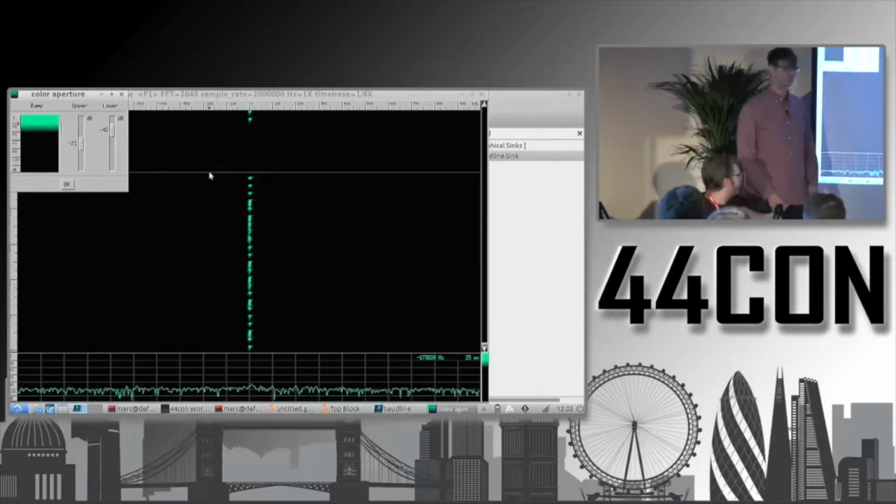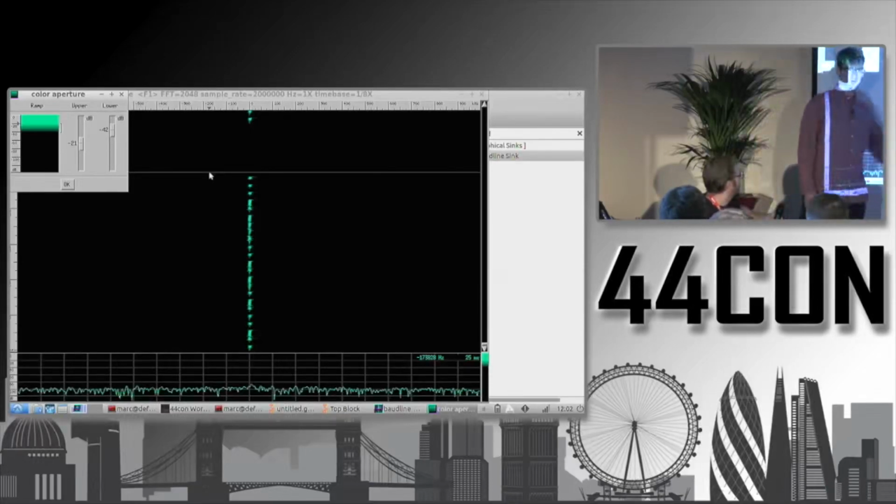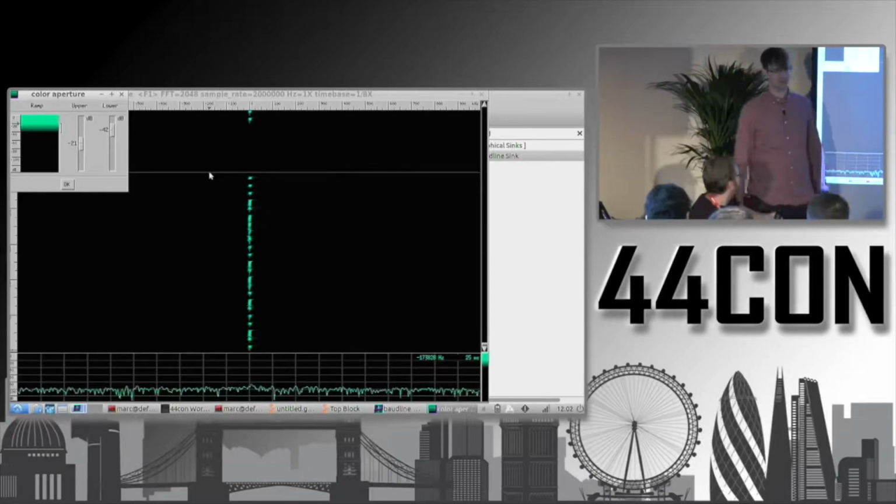So we can look at the insight that we've gained from looking at the channel here, that we see a single center frequency and that there's no deviation. There's just a single frequency that the protocol occupies. So if we saw the frequency jumping back and forth, that would indicate FSK, since it's on a single channel, and instead it's the power that's being modulated, then it's something amplitude driven.